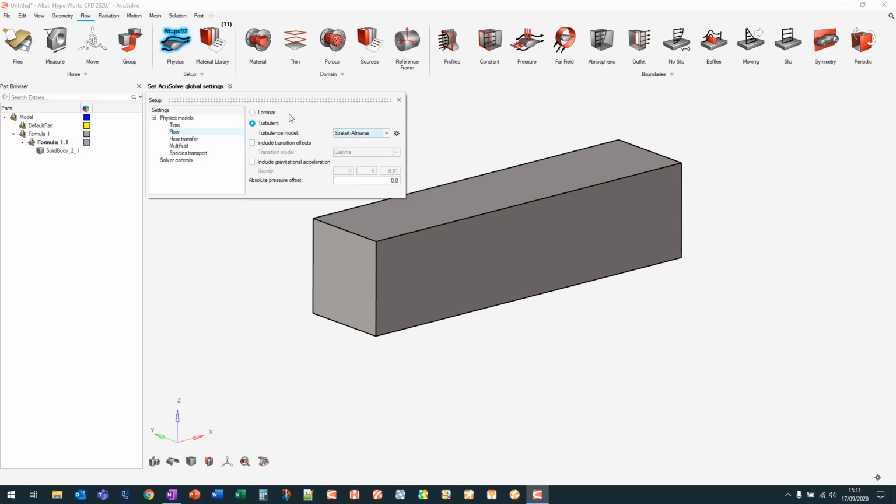So HyperGraph CFD knows the buttons that you want to press beforehand. So another example is if you're running heat transfer, you won't be exposed to any of the heat transfer functions unless you explicitly turn heat transfer on. So we'll go back into time, we'll put it to steady state. Let's say shear stress transport, again this is up to you on to what turbulence model is best for your use, but in this case we'll go with SST.